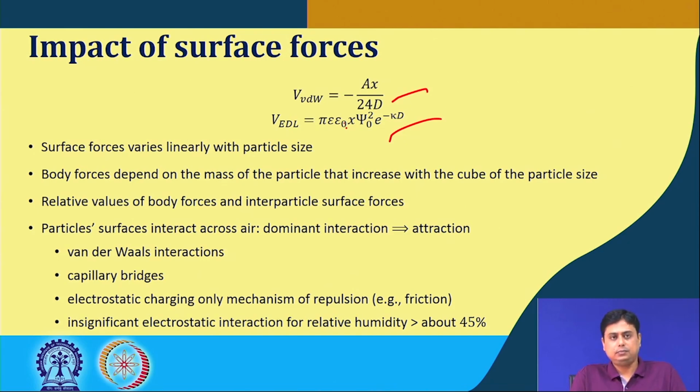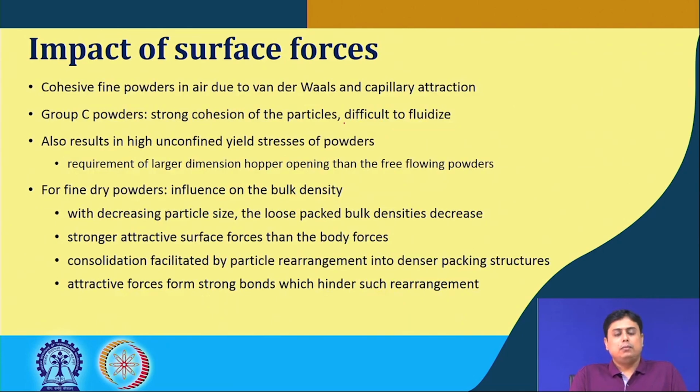But this becomes non-significant when the relative humidity of the atmosphere is greater than about 45%, because this electrostatic charge rapidly decreases with humidity. So, cohesive fine powders result when in contact with air because of van der Waals and capillary attraction.